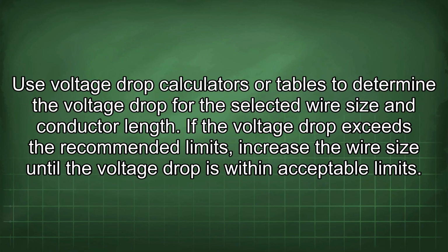Use voltage drop calculators or tables to determine the voltage drop for the selected wire size and conductor length. If the voltage drop exceeds the recommended limits, increase the wire size until the voltage drop is within acceptable limits.